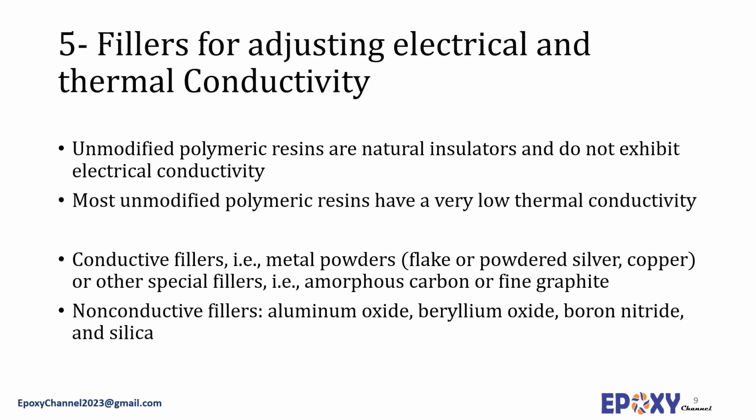Conductive carbon, amorphous carbon, or fine graphite can also be used if some degree of conductivity can be sacrificed for the lower costs. Conductive adhesives are generally formulated from base polymers that are low viscosity thermosetting resins such as epoxides. Where elastomeric properties are required, silver-filled flexible epoxy and silver-filled silicone rubber systems are commercially available.